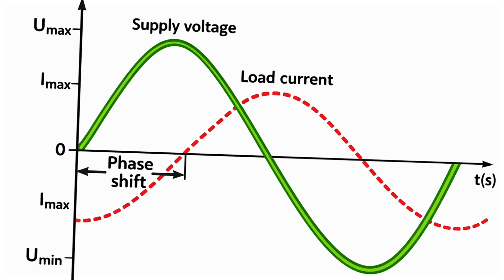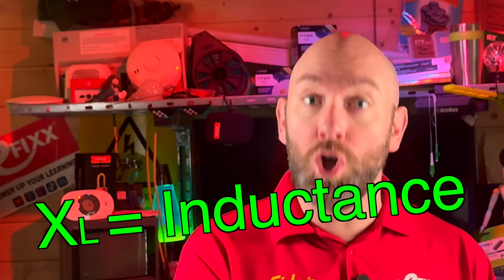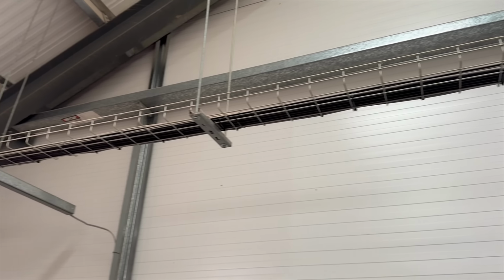During a surge event, there is a rapid rise in voltage. Because of that rapid rise in voltage, there is a change in current, and that change in current is resisted, and that resistance is called inductance. And inductance can create additional voltages along the length of the cable. So the longer the cable, the higher the inductance, so the higher the potential voltage.